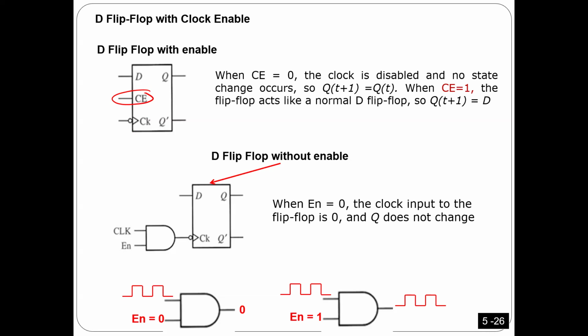So what I'm saying here, guys, is that sometimes the flip-flop has an enable. We should understand how it's going to work under enable. If the input is 0, that means this one is disabled. That means the output here, for example, if it is 1 1, no change. It's going to continue 1 1. So even if you put 0 or you put 1, no change. You are not going to see a change.